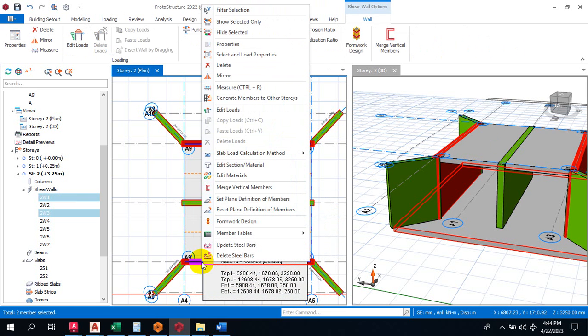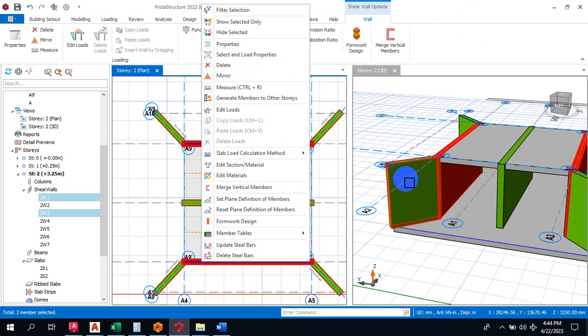You know that in Prota Detail there is a template for Culvert, but if you observe, you will discover that that particular template does not generate any reinforcement details. So it is very important that you do your modeling here, because that particular template will not give you what you are looking for, except you want to just generate an elevation for it.